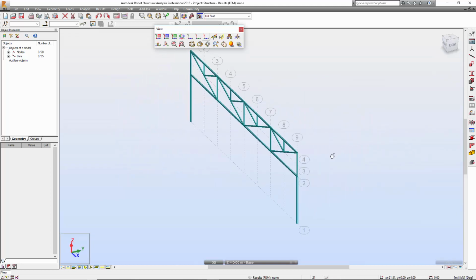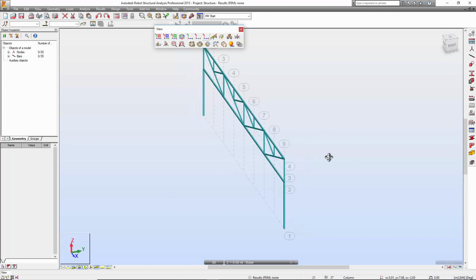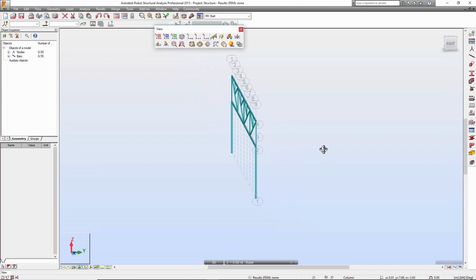For example, the structure out of plane in the y direction, along the y direction, if anything touches this one, although we don't have any loading applied, this structure could easily fall down. If you don't have any restraint of the structure in the y direction, then y is unstable. So y is unstable.